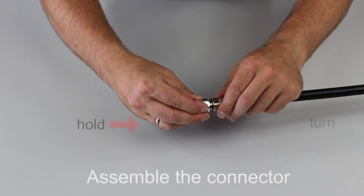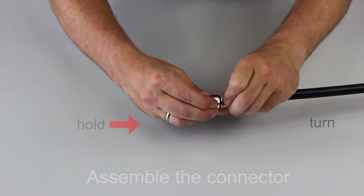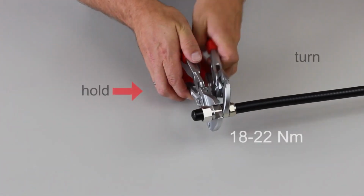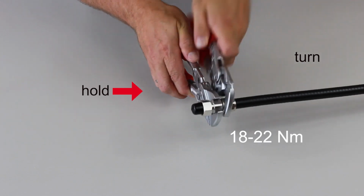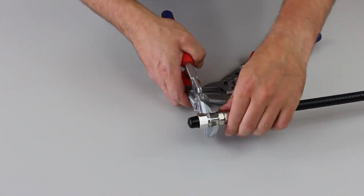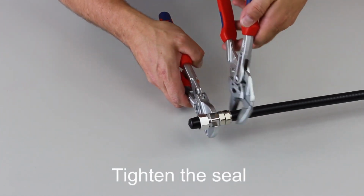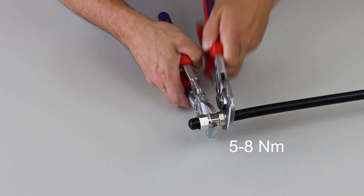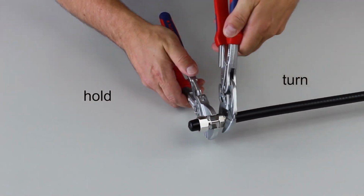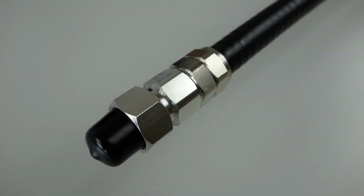To assemble the connector, attach the upper part and screw in the back of the connector by hand. Then use the pliers to tighten the connector. It is important that the front part of the connector remains still. Repeat the same process with the seal. Screw in the seal by hand and then tighten it with the pliers. Hold the front part of the connector with pliers to prevent it from moving.